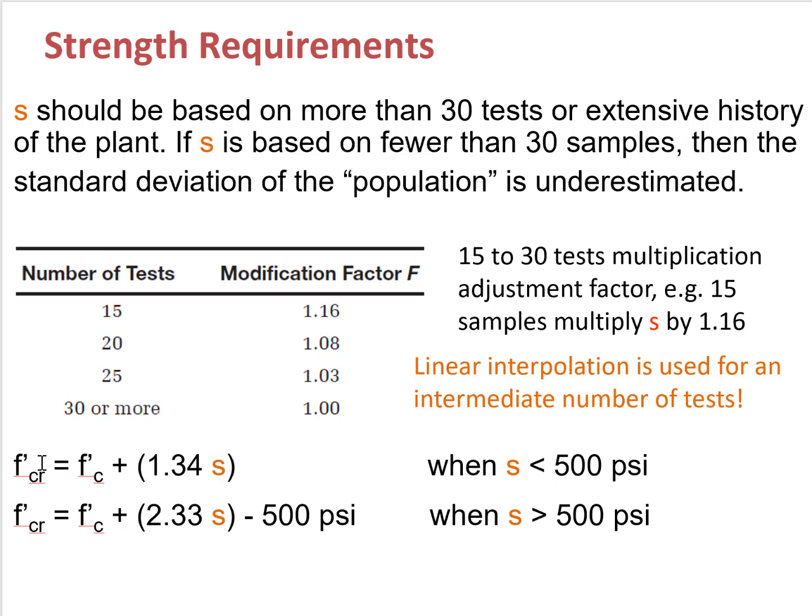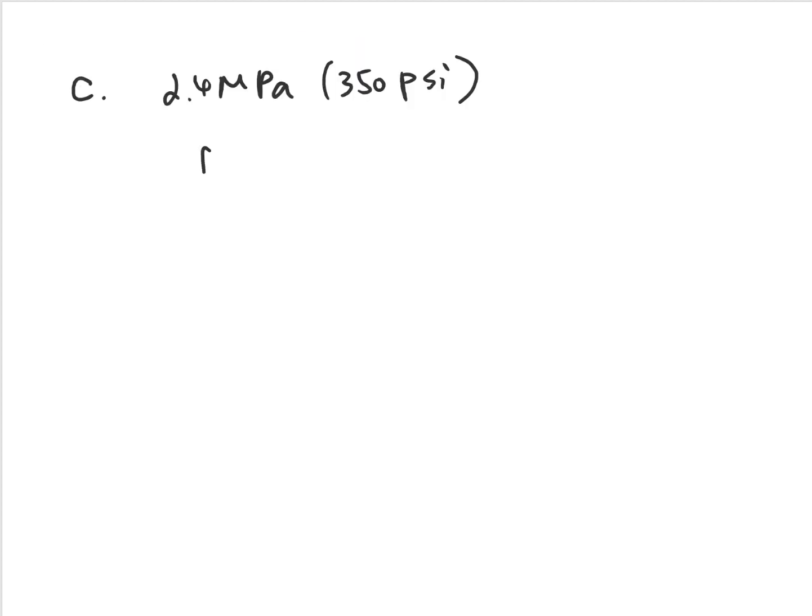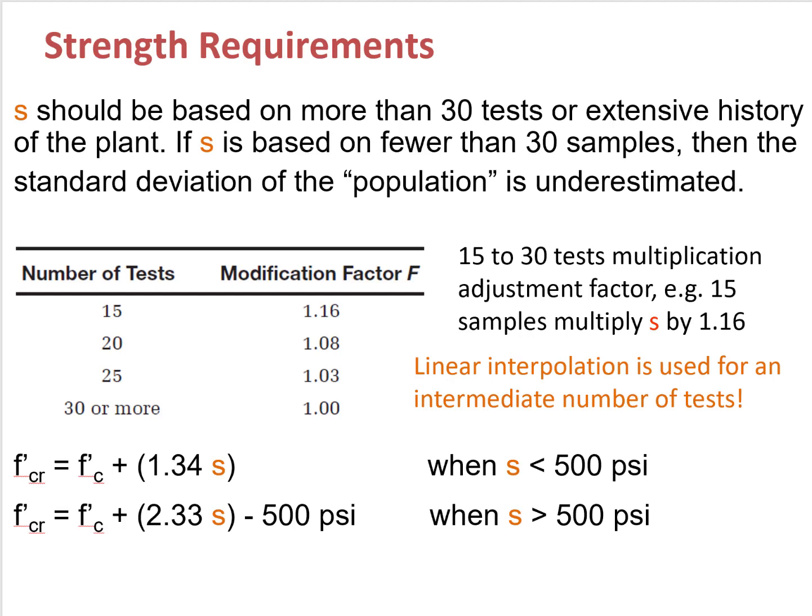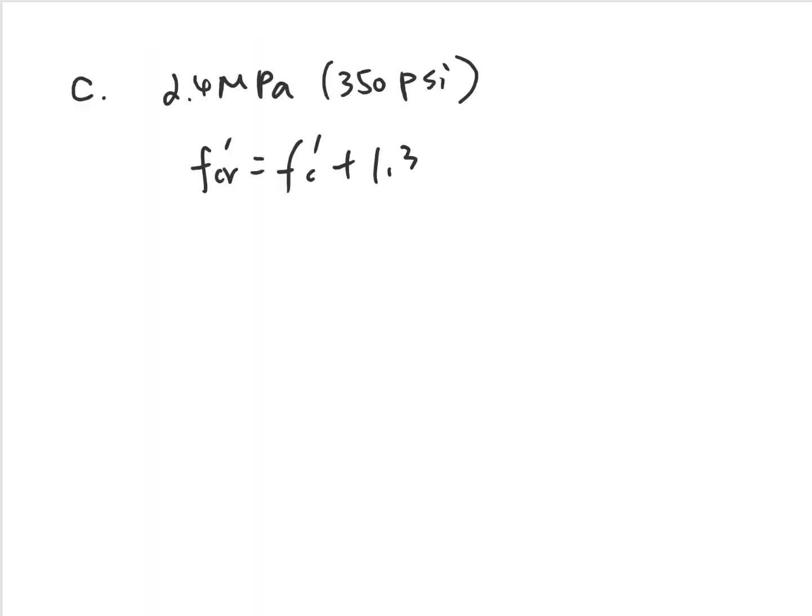So f'cr equal to f'c plus 1.34 times S, and S is provided, so you can calculate. So this should be equal to 4970 psi.